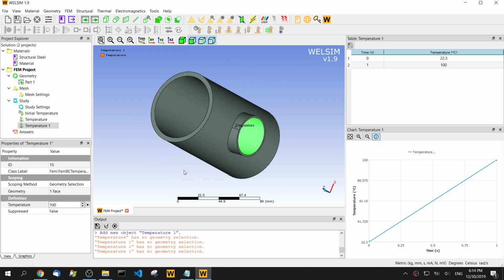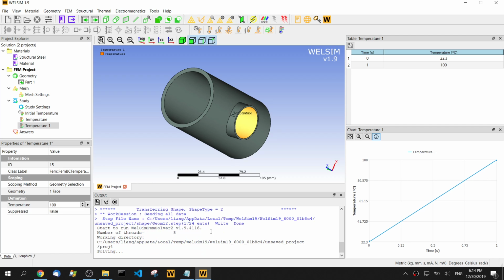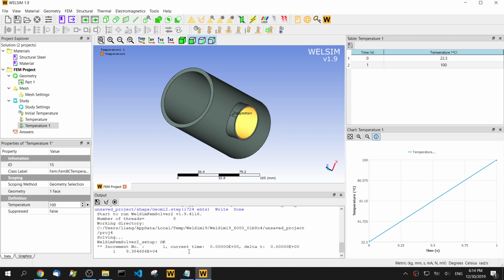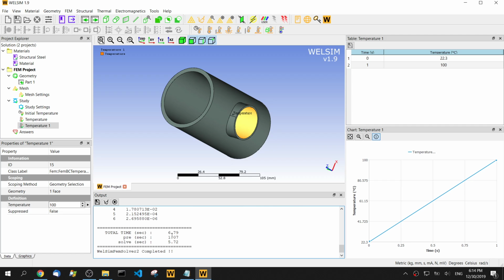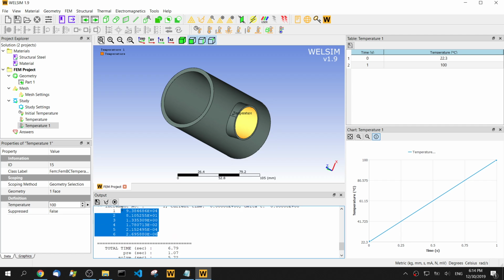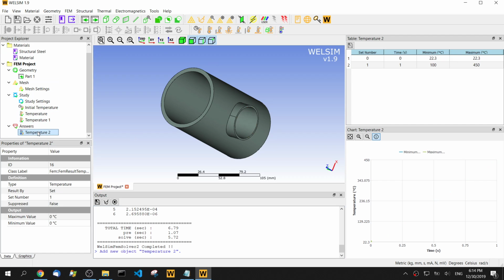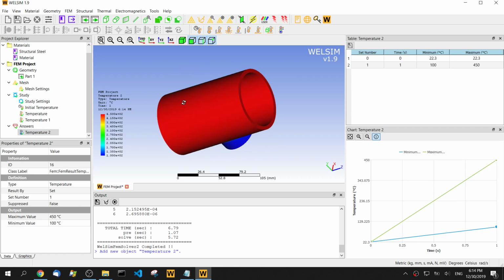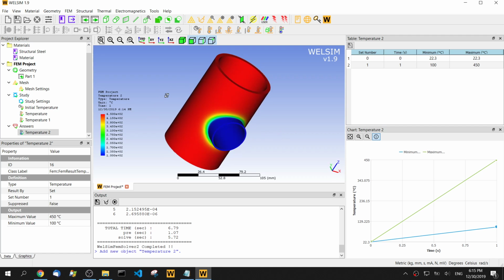That's it. We've set all these boundary conditions and materials, and note that the material is nonlinear for the conductivity. Let's click the solve button. Let's see the Newton solver is working now. You can see there are 6 iterations here, and the problem is solved. Let's add the temperature and see what it looks like. This is how the final temperature distribution looks on this body.